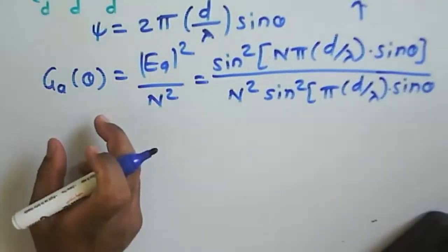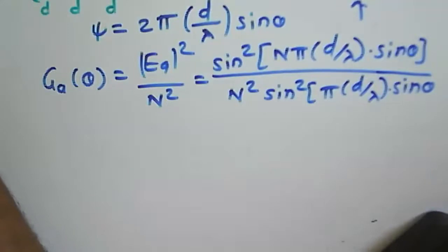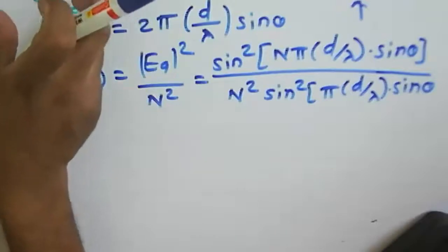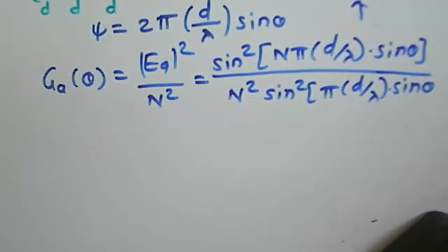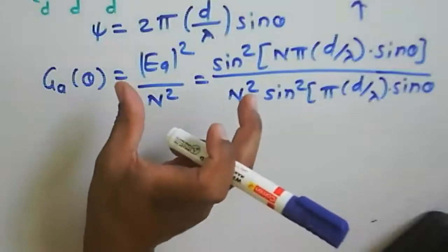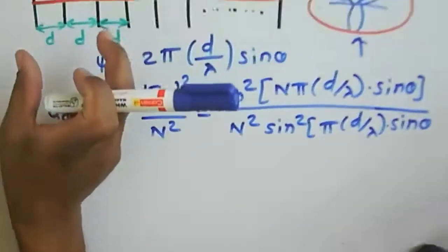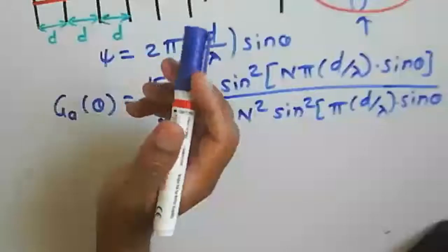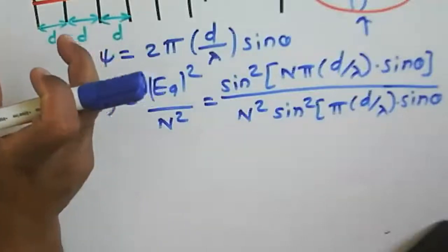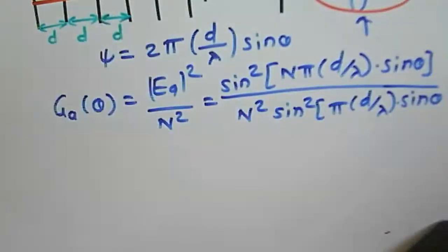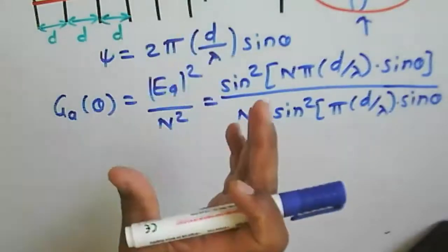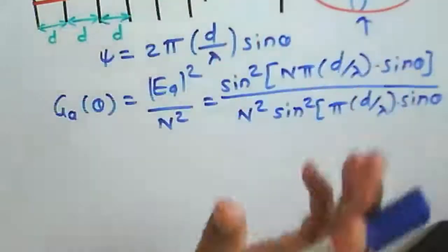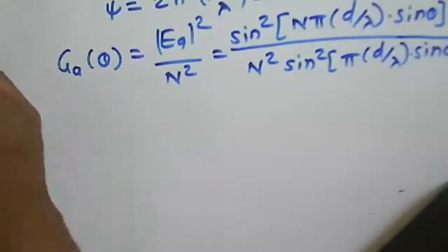Now this one is the radiation pattern of the signal, and here we consider the spacing between the elements, that is the d here. So at what value of the spacing between the elements will we get the maximum radiation here? For that purpose, what we need to consider here is what will be the radiation pattern of an antenna, and from this radiation pattern, what will be the half power beamwidth. So half power beamwidth means what?